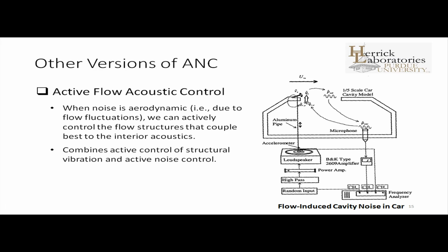There's a lot of interest in the aircraft world in delaying boundary layer transition, right, to try to reduce drag on aircraft surfaces. And there are various active means, suction and so on, involved in doing that. And the same kind of things actually can reduce the noise in the interior that's generated by turbulent boundary layer noise, for example.